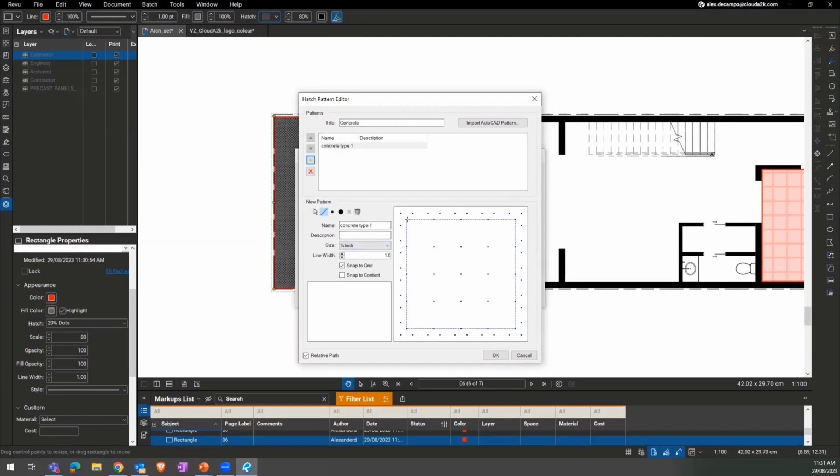Then you get this little area here. Same as before, that dashed blue line shows the extreme edge of where the pattern begins. Anywhere you go over that line, you can see that little gray line appears on the right hand side. That's where it's looping. So if I add something at the top, you can see that it appears at the bottom. That's where it's going to be connecting. These patterns are stacked on top of each other, next to each other, to continue and become a whole region. Let's just clear it out for concrete.